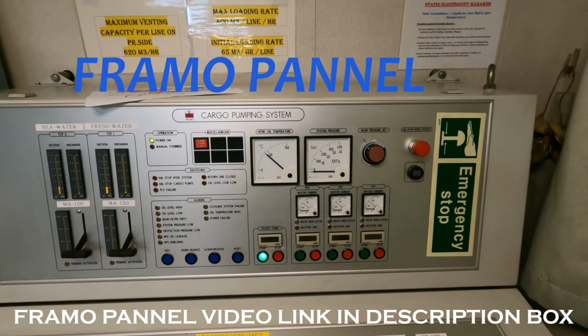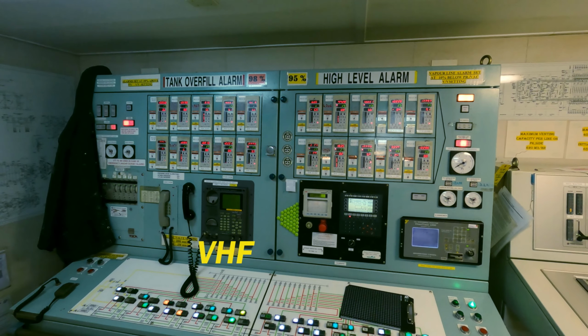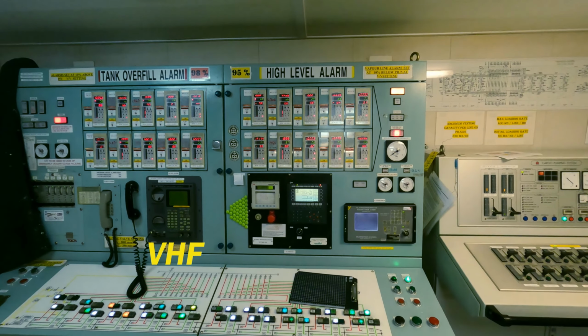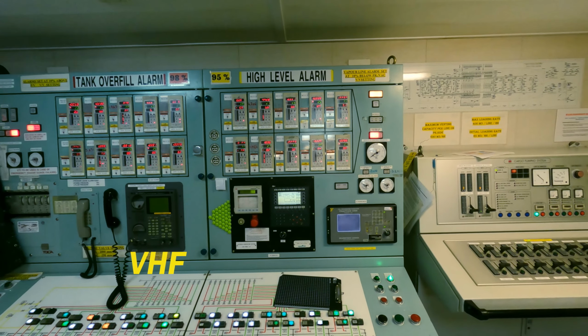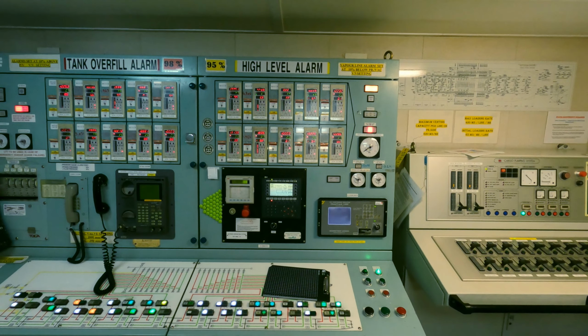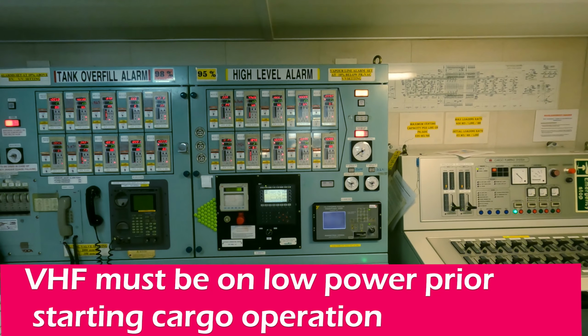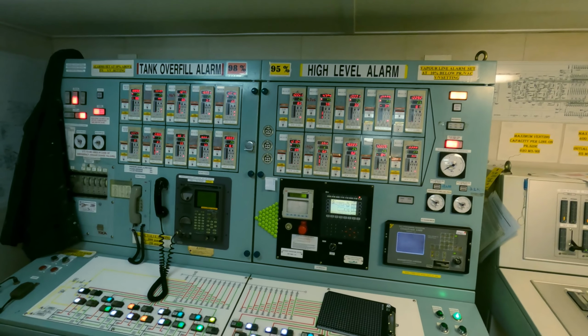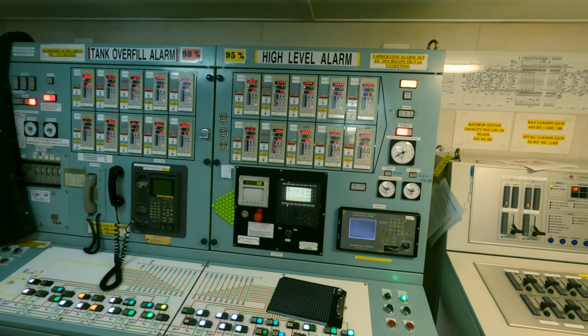You can watch that. Next we will see the VHF, which is there in all CCRs, and sometimes it is used as the primary means of communication and sometimes as the secondary means of communication with the terminal. One important thing about VHF is that it is to be kept at low watt, or 1 watt as we say, before starting the cargo operations. Now I will show you how to put a VHF on low watt.